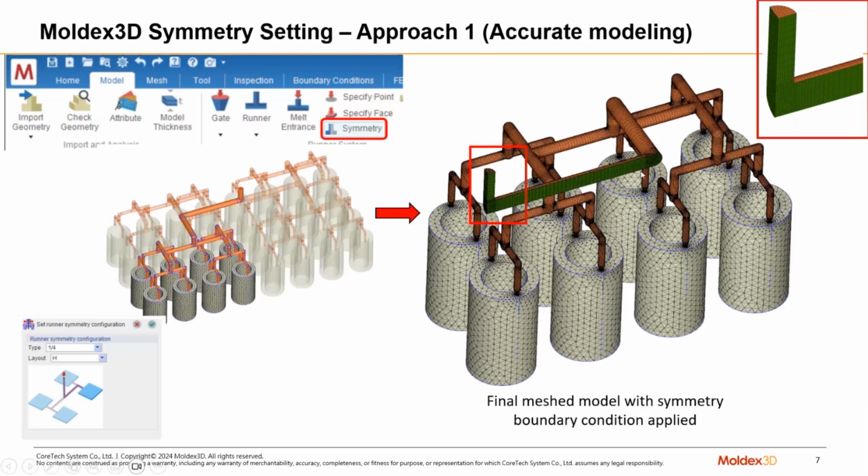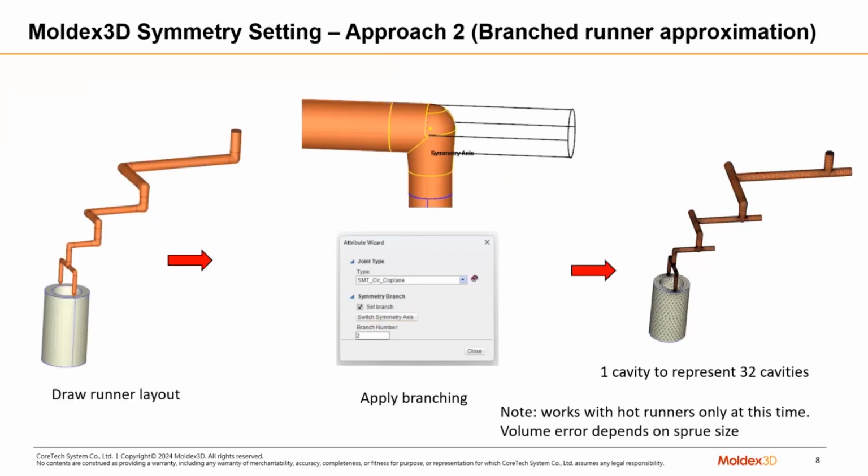It's using boundary conditions, so when you select symmetry, it's assuming that there are three other quadrants in this. So even though the simulation is run on this one, it's assuming the other three quadrants exist. Yes, you're not going to see the results on those, but the pressure prediction and everything is considering all four quadrants. So this is basically showing the button, how to go about setting this up.